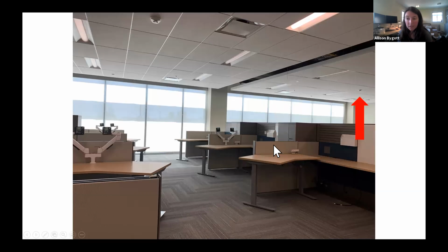This is like your standard cubicle office building. We have a daylight sensor over here. Again, it's so daylit, even though the shades are down, that the lights in the daylight zone are at a minimum dim level. What was interesting about this building was these are kind of bright too. And what would have been nice is to apply an upper threshold to kind of take them down a little bit, because there's still plenty of daylight, even though we're way back in the space.